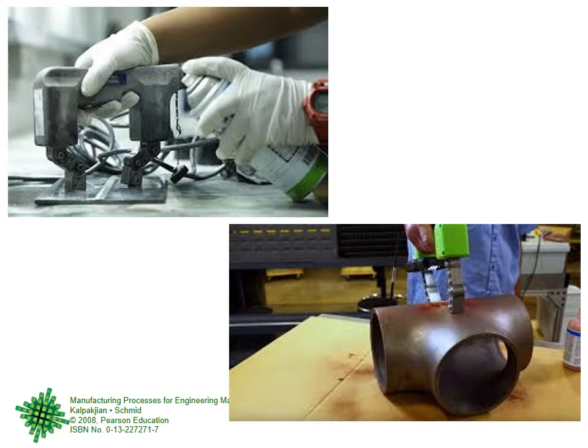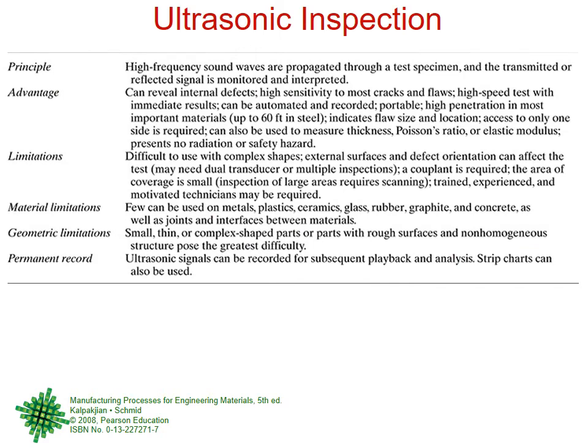I have done it myself when I was in the field as a quality control inspector, both liquid penetrant and magnetic particle inspection. Ultrasonic. The name is very clear. Sonic means anything related to sound, and ultra means at a higher level, right? So the principle, high frequency sound waves. Sound waves sonic, high frequency sound waves ultrasonic.